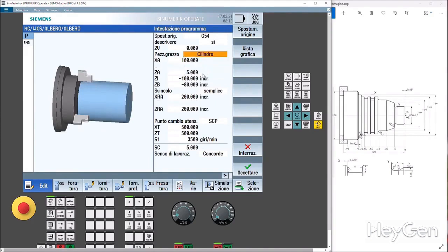If I'm starting from a preformed piece, I can't do it. So I either have to do roughing with a virtual tool using very aggressive parameters, which kind of tricks the machine, or I have to settle for standard shapes like cylinders, tubes, centered parallelepipeds, or polygons.